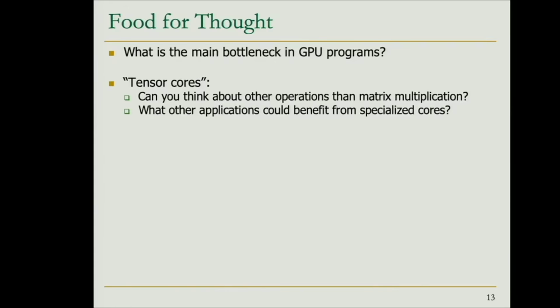And the question here is: is it possible to use these tensor cores, which are super fast and very nice, for other applications? Well, this is something that some people are exploring these days, trying to see how to slightly modify these tensor cores to be able to do more computation. For example, there is a very recent proposal in MICRO 2019 about utilizing these tensor cores to execute sparse matrix computations as well, which is going to be more and more important for neural network training.